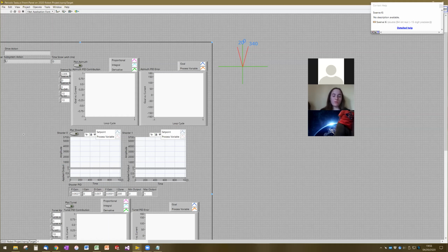Yep, correct. So we've already got real friction that's doing the damping physically in our system, so we've been able to get away without a D term. And then the reason we don't have an integral is, the motor actually does a very good job of getting the wheel to the correct position. The inertia of that wheel, the mass of that wheel, is fairly small relative to other things that we control, like an elevator. And so your steady state error tends to be pretty low.